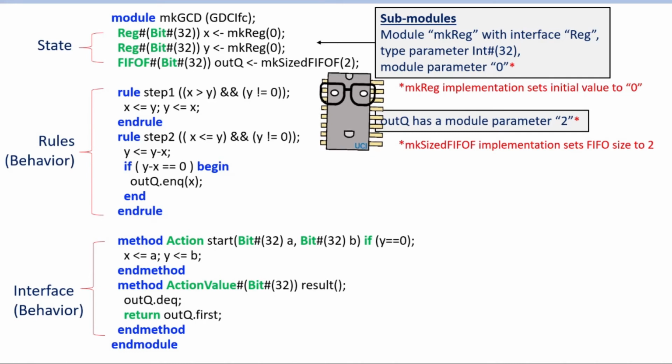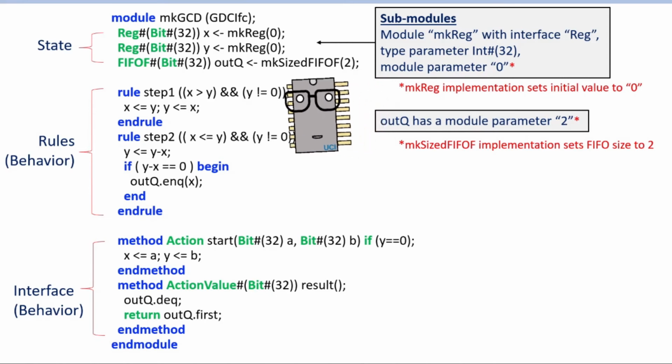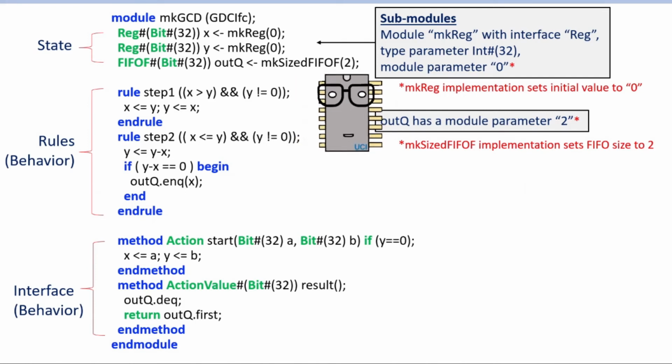But in the hardware context, unless you are building something complex which uses off-chip memory or block RAM, even when you use block RAM, each of these slots in the queue for out queue is taking up explicit resources on the chip. It is taking up LUTs, it is taking up CLBs, etc. So if you give it a size 2, you only have size 2.